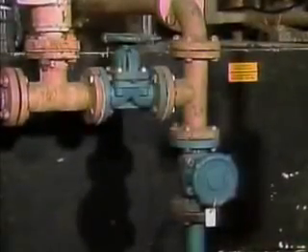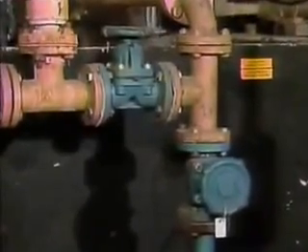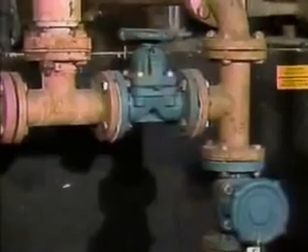When the hand wheel is turned in the open direction, the diaphragm moves upward, allowing fluid to flow through the valve. The diaphragm in a diaphragm valve isn't subject to uneven wear. So a diaphragm valve can be used both for throttling and for on-off service. The diaphragm also makes a tight seal that keeps fluid from contacting the operating parts of the valve.